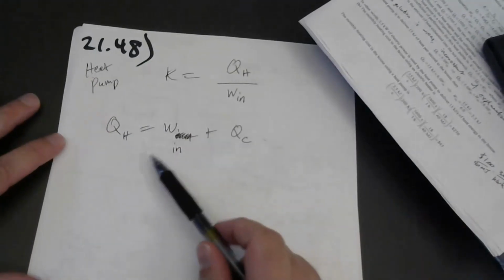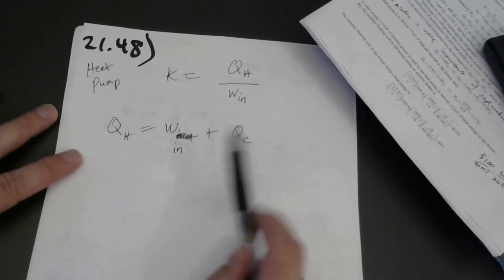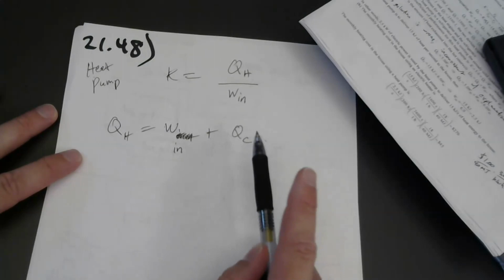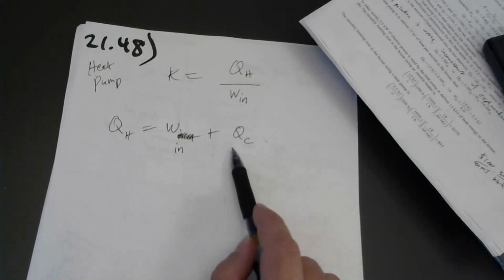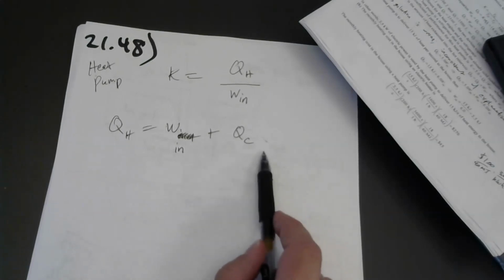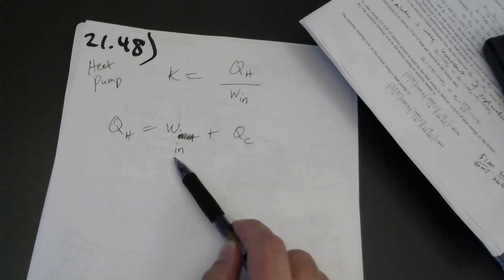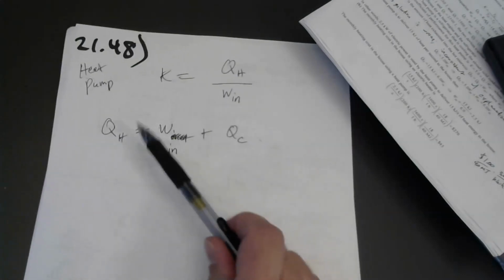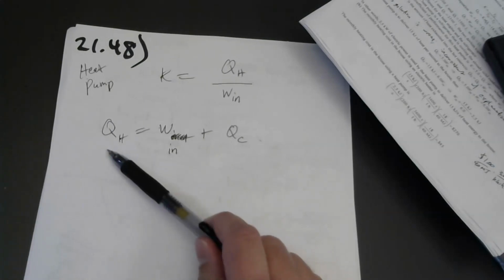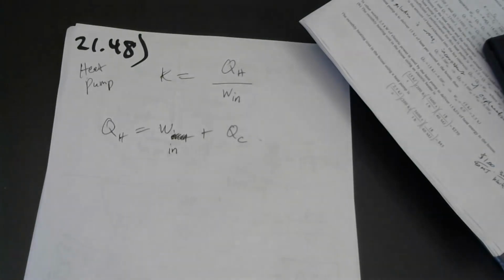So it's a very simple relationship. Think about your freezer box, back to the previous problem. If you scoop out 100 joules from the freezer, and to do that you had to pay for 20 joules from the power company, a total of 120 joules is actually being dumped into your kitchen. Did you know that the electrical energy that you're drawing from the power company with your refrigerator is actually being dissipated thermally within your room?